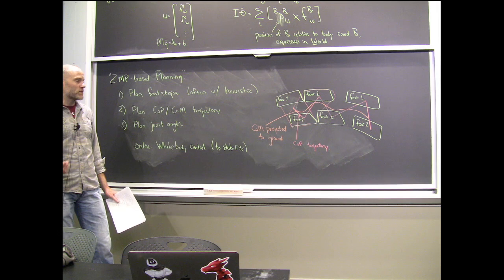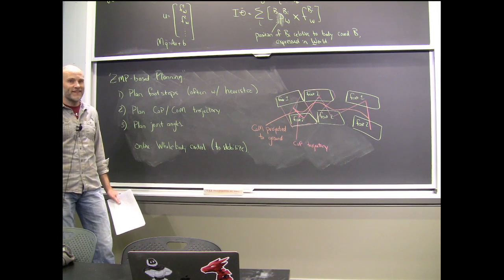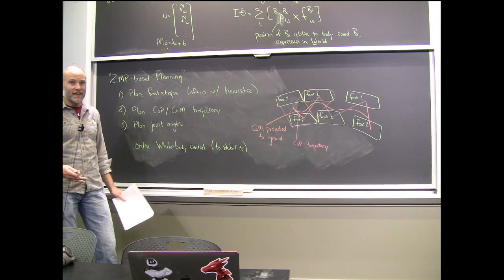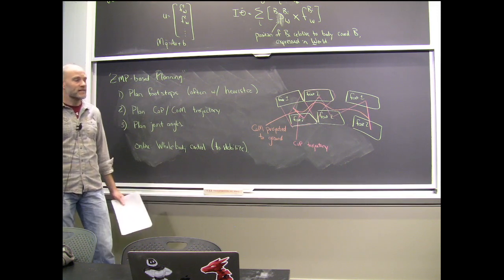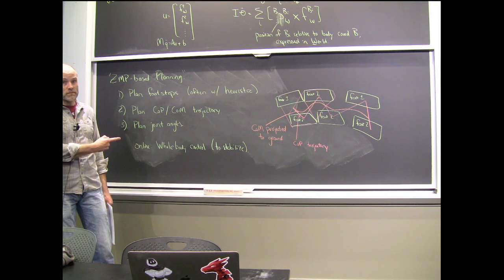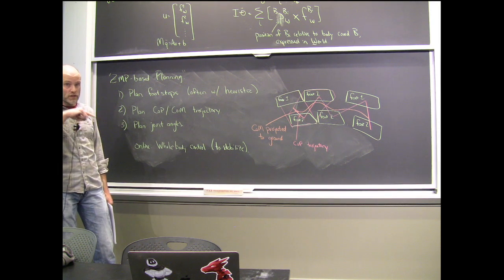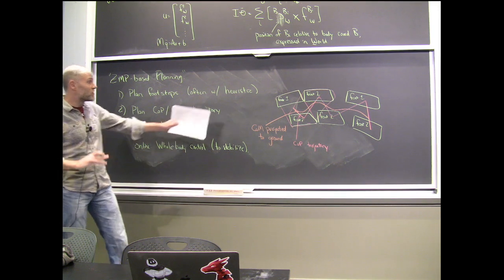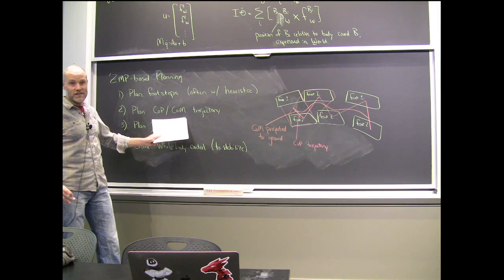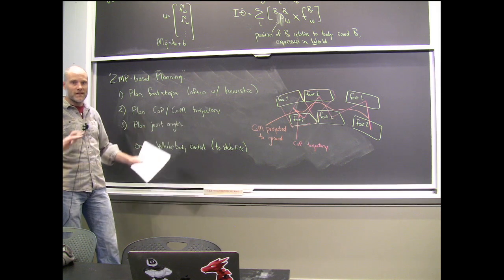So that's a great question. So the passive walkers had these big curved feet, right? And they walked beautifully, right? And Asimo has these big flat feet, and people don't love the way it walked, right? But the math works better for the flat feet case, right? So the curved feet, I think, doesn't jive with this very well. You're going to always have a constraint of a point, and the kinematics of your decision at this level demands this. There's no room for optimization in here after you've picked the footstep, so there's not a really nice split there.